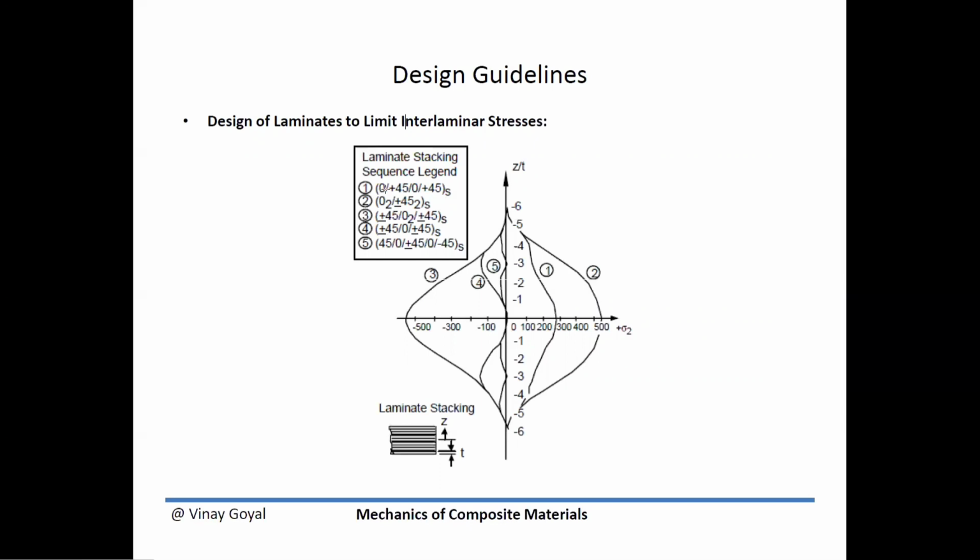You can see here I have 4-ply symmetric laminates in all these cases, and one of the things you can see is that the one that gives me the least interlaminar stress... this plot here is the interlaminar stresses through the thickness. And what you see here is the interlaminar stresses are the highest for stacking sequences 2 and 3. That's 2 here and 3 here. And so those are resulting in huge stresses. But number 5 results in a much better situation.